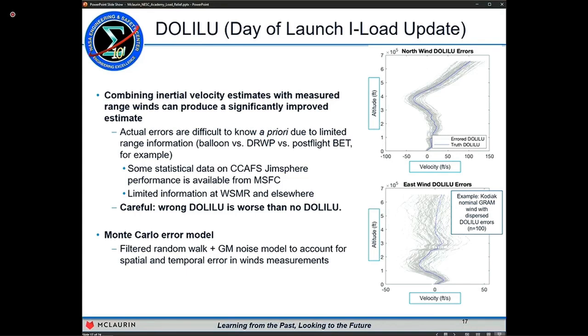A little short on time, so I'll go very quickly through this, and of course the slides are available for review. I want to make sure we leave enough time for questions, but essentially what we have done is we've taken those gravity turn equations and added a term due to wind. This is just a standard term due to wind, so now instead of just the lateral velocity over V, you've got the wind velocity over V. And it turns out if you can measure the alpha,